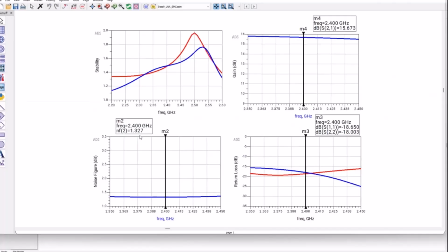That's why the transistor model, remember, my target was 1.4. I said you should pick noise figure minimum to less than or equal to 0.7. And my transistor had close to 0.6. All right. So it was already touch and go. And that's why you can see you are almost there.